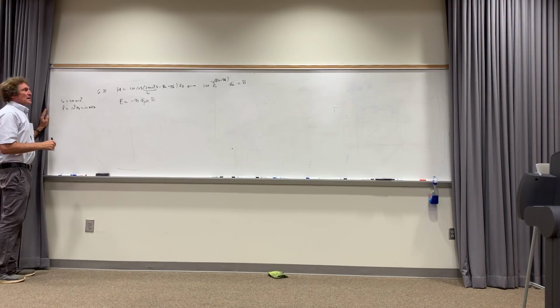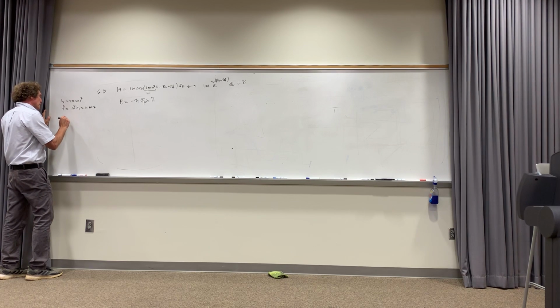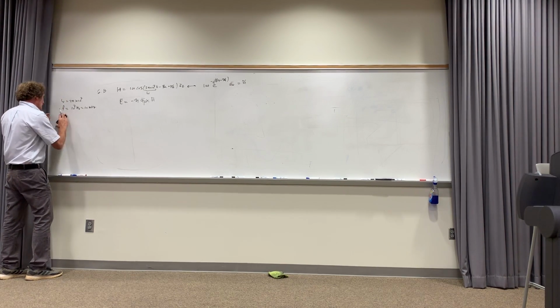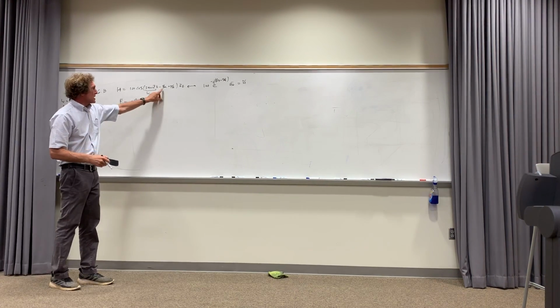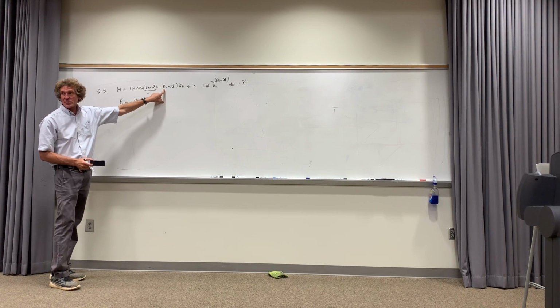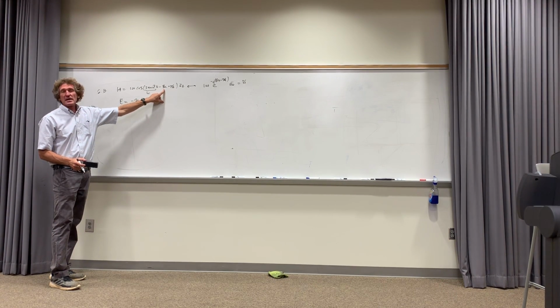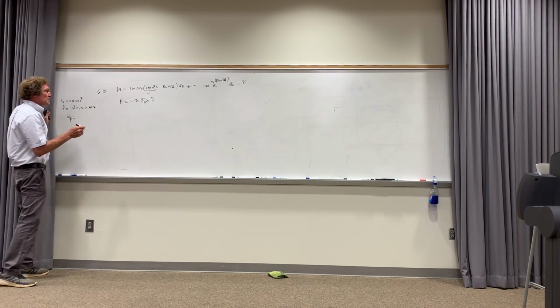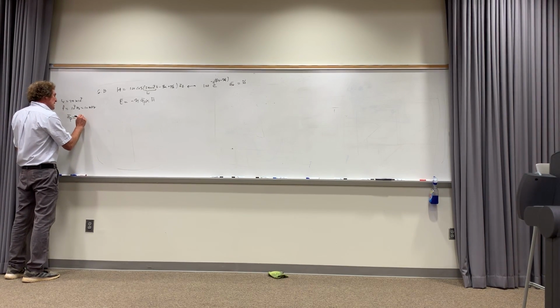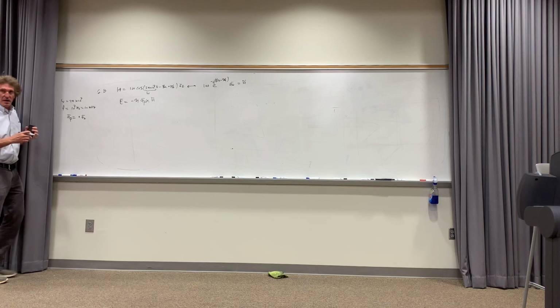Now I look at this, and I'm going to get the direction of propagation. This is going to be a unit vector in the direction of propagation. The way you get this is really taking a look at the spatial variable, which is x in this case, and see if it's beta times x. It's going to be the spatial variation in terms of phase. If that's a negative sign, it's moving in the positive x direction. If it's a positive sign, it's moving in the negative x direction. In this case, we only have an x, we don't have a y in there. So it's moving in the plus ax direction. Everybody follow me on that?